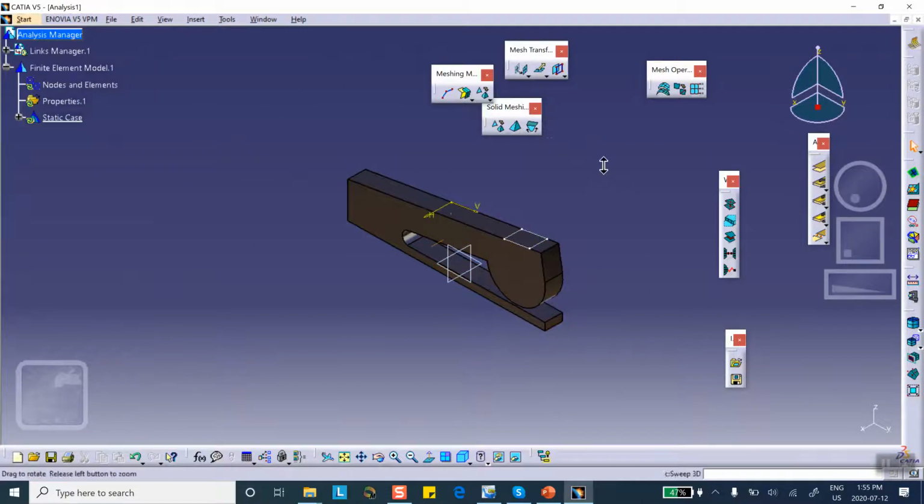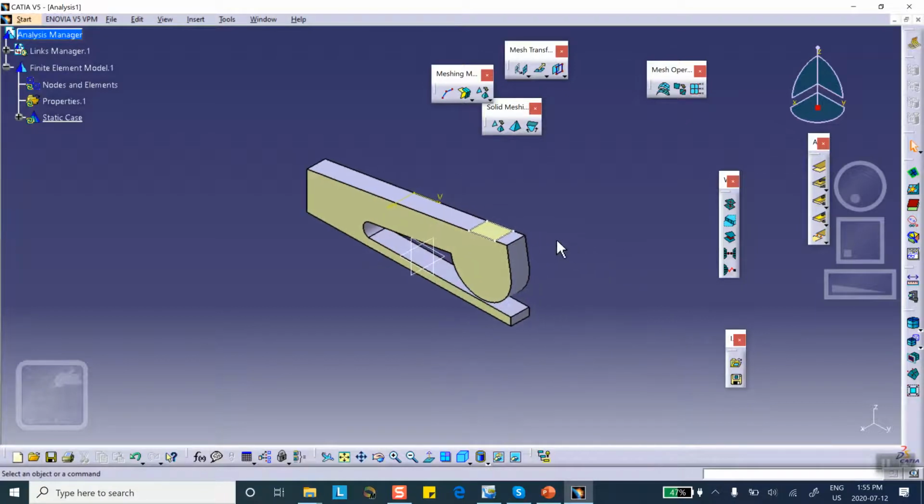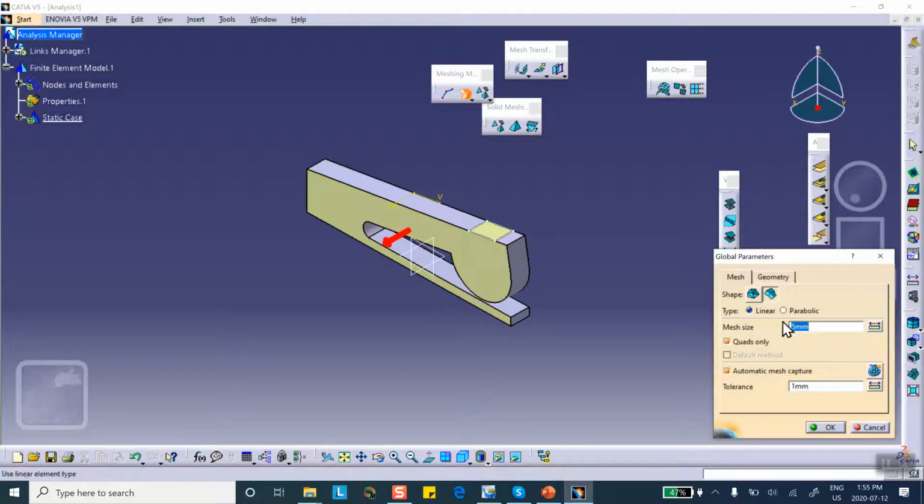Okay, very good. Now, let me change the rendering here. Okay, good. Now, surface mesh is right here. This is the meshing method, I suspect. I'm not sure what the thing said, but the surface mesh is right there. You select that face, the extracted face, and you give it the size of the element that you want. Since I want all quad elements, I clicked on this box instead of that one. That one gives you a combination, this one gives you triangular, and this one quad, and I want quads only.